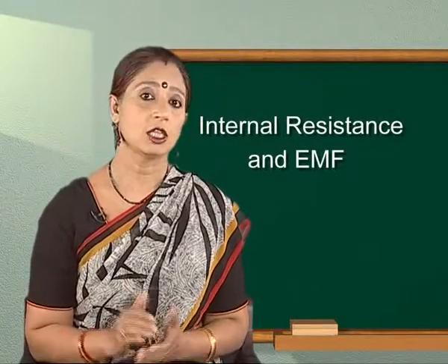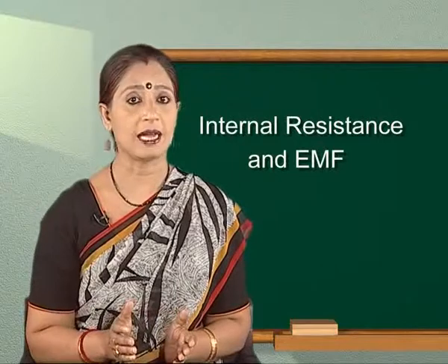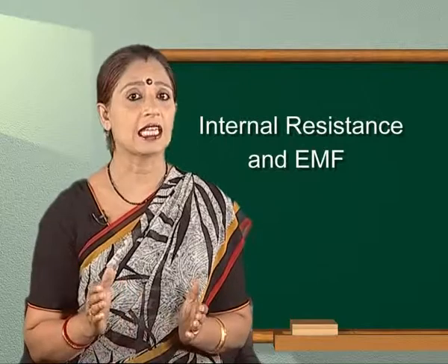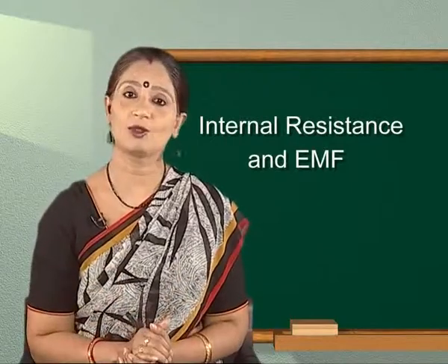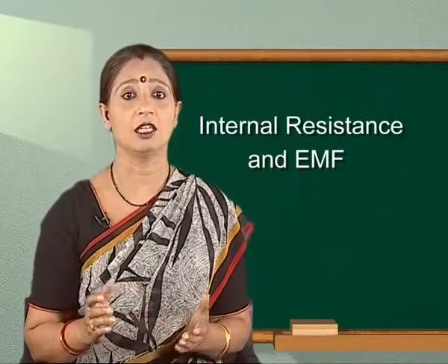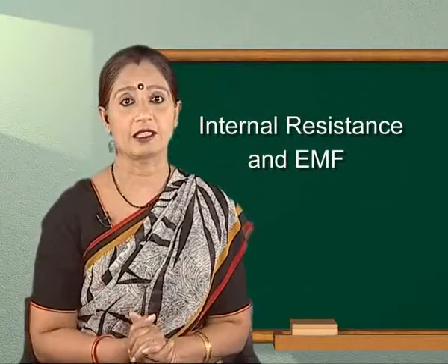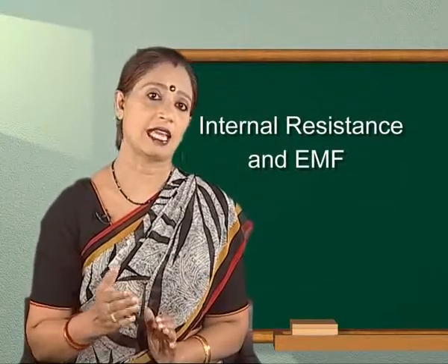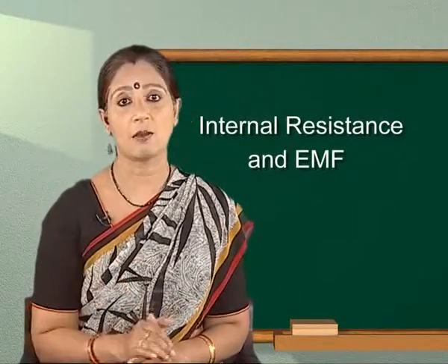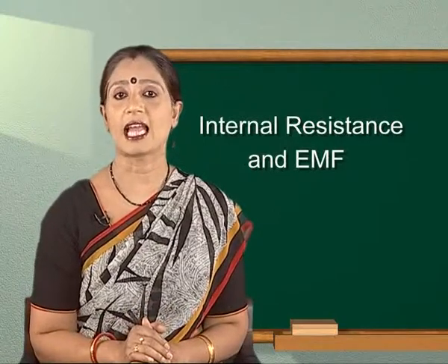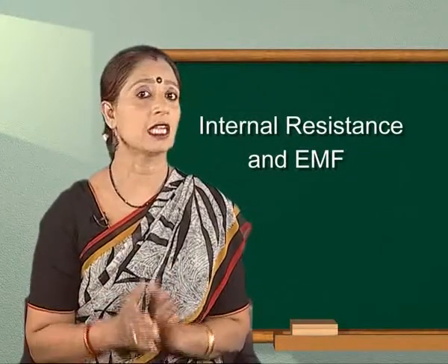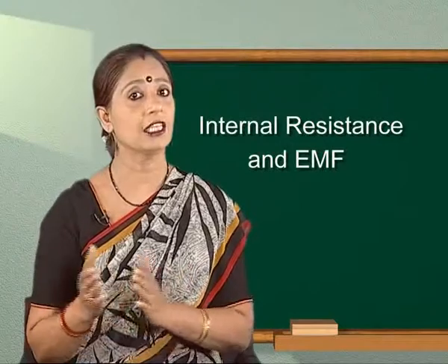If you measure the voltage of a failed cell or battery which is disconnected, you will usually find that it has a nearly normal voltage, so a voltmeter is not a useful tool to judge the degree of life left in the cell or battery. If you connect the cell or battery to an external resistance, then you will find that its terminal voltage drops. This can be interpreted as dropping most of its voltage across its internal resistance so that it is not available for external service.